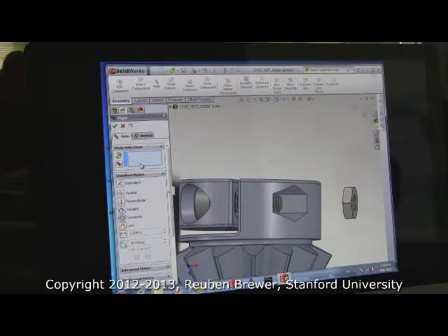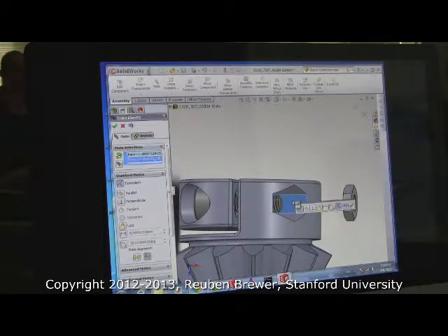So look on my screen for a sec. If anything appears here, you can't drag things around safely. This is the most common mistake in SolidWorks assemblies. If you press the wrong things for the wrong type of mate where it doesn't make physical sense, it will chug on it for 15 minutes and die. And this happens to me on a weekly basis. It's super annoying. Be really careful what you press here. You don't want to select things that can't be tangent and press tangent. It'll kill the program. So press this surface here and any one of the surfaces on the hex hole.